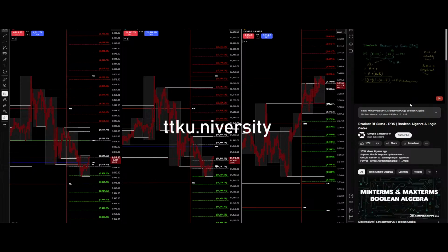a or b. This is the first term. We don't need to convert it, since it consists of both the variables. And now we converted this a to this entire part. So we substitute it and we get a or b, and a or b complement. So this is our final answer after conversion of product of sum to standard product of sum form.